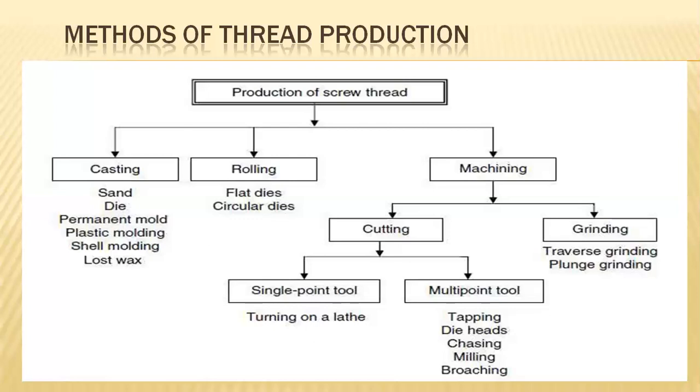The single point cutting tool is normally used in the lathe machining process, and the multi-point cutting tools include tapping, die heads, chasing, milling, and broaching processes.